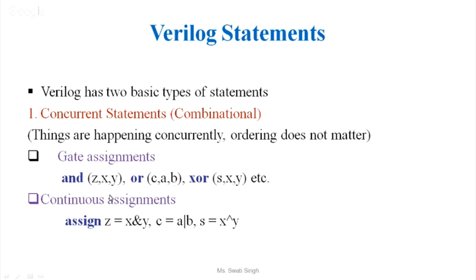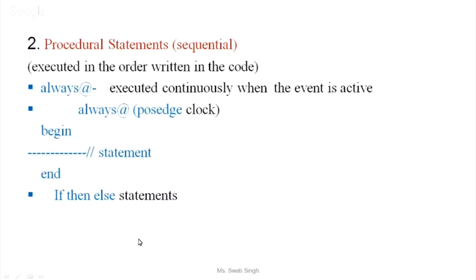In continuous statement, you write the assign operator. Assign, just write z, your output, equal to x and y. So it is better to write this gate statement. You can use a continuous statement, use the assign operator and write your statement.